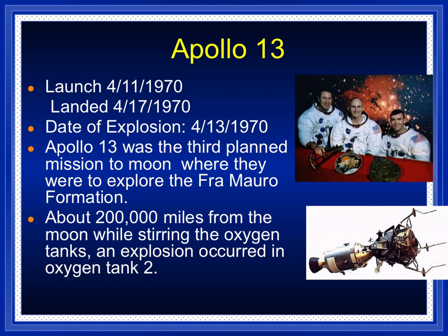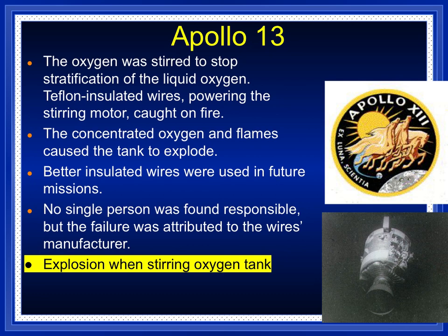About 200,000 miles from the moon, while stirring the oxygen tanks, an explosion occurred in oxygen tank 2. The oxygen was stirred to stop stratification of the liquid oxygen. Teflon insulated wires powering the stirring motor caught on fire. The concentrated oxygen and flames caused the tank to explode.